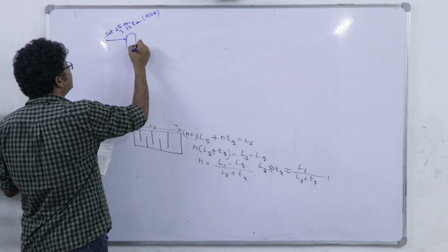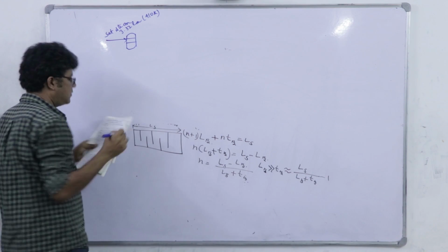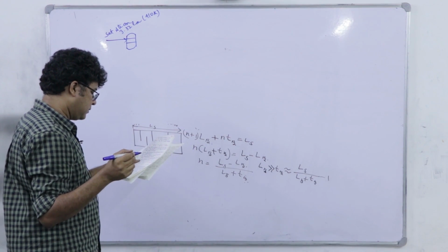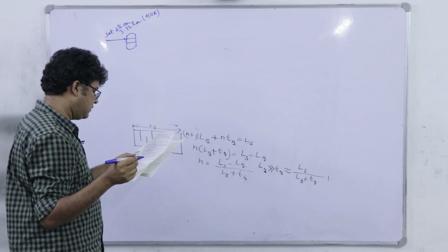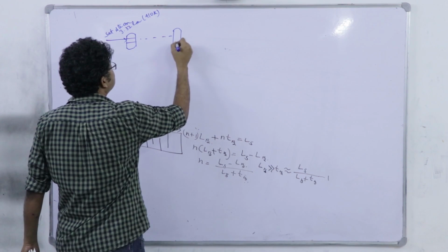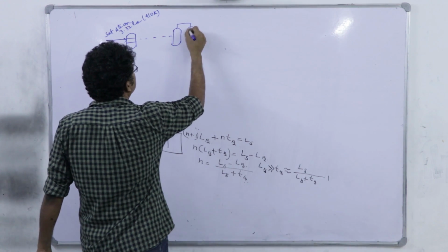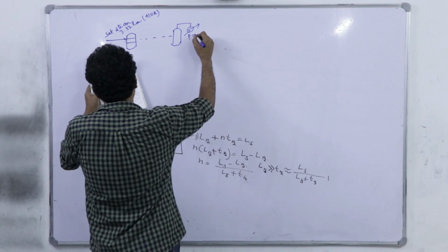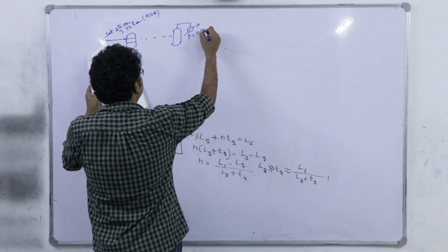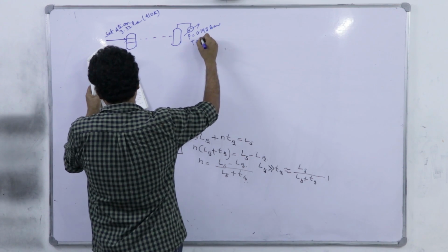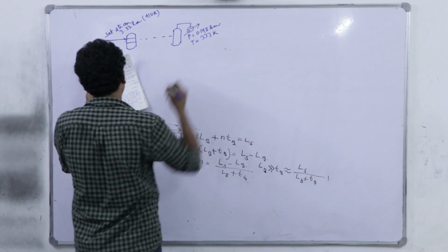So here we have the first effect, this is the steam chest, and the residual pressure in the condenser attached to the last effect. So here we will have the last effect, here we have the condenser. Here the pressure is 0.195 bar, respective boiling point is 333 Kelvin.